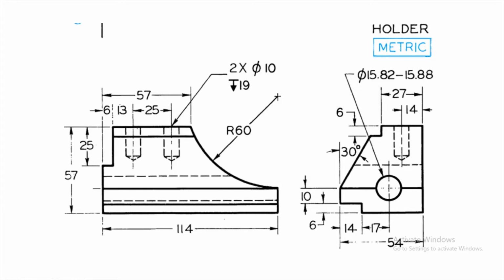We have another hidden line coming here in the side view. So this is the horizontal hidden line. When projected onto the other side, it actually comes from the intersection of the two faces formed by the two vertical and the horizontal line here. So this corner, when extended deep inside, is hidden when seen from the right side. We have already covered these two hidden lines here. They correspond to the hole that is being drilled from the right face with the circle here, which has a diameter of 15.8 to 15.88 as the limits. So this completes the visualization or interpretation of the view part.